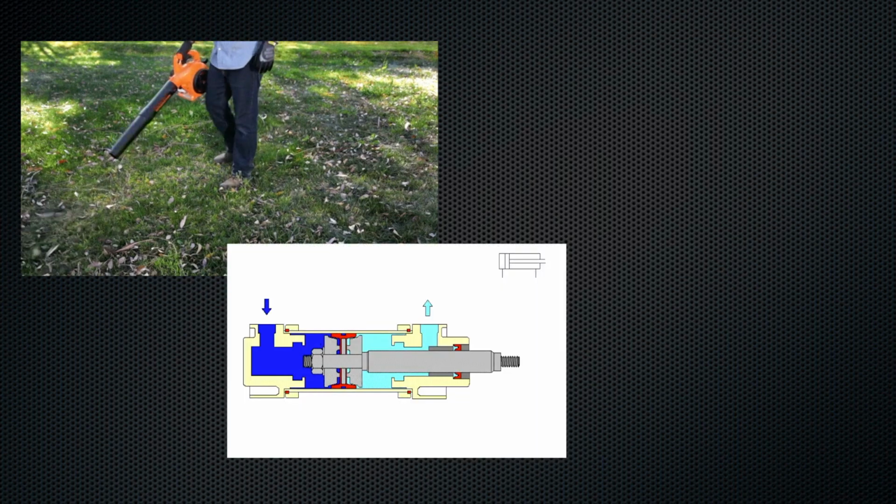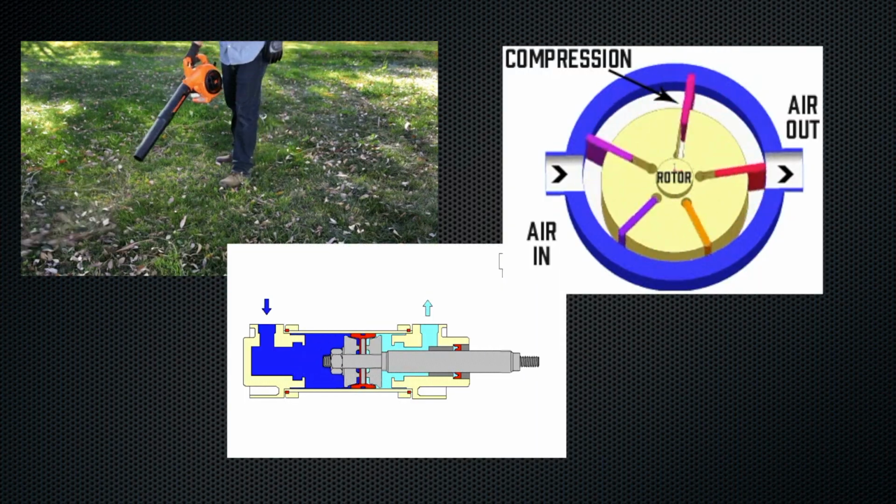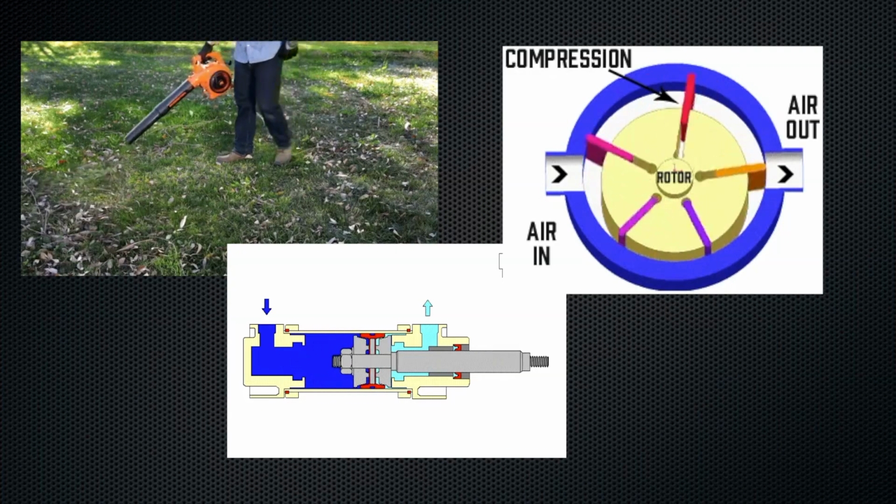And in reality, you use more than just the high pressure, because as we have higher pressure, we have an increase in leaks and in unregulated use of air. Unregulated compressed air use is blowing applications and tools and air motors and stuff like that, which we're going to address in some detail in episode 2 of this video series. But the combined effect of raising the pressure and therefore increasing the unregulated use of air is not subtle, and it's why you save so much money by lowering pressure.